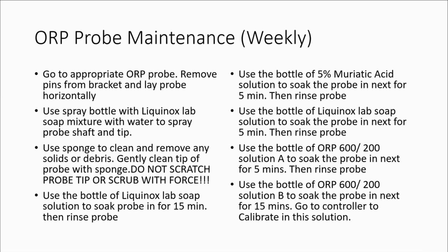So we set our chlorine dosing pumps in hand at that point, so the controls don't take over and do really crazy things. Before this, we look at what our dosing rate is and set it in hand at that, which bypasses the SCADA control systems. And then for that 45 minutes, we're basically in the hold. It's holding the same.